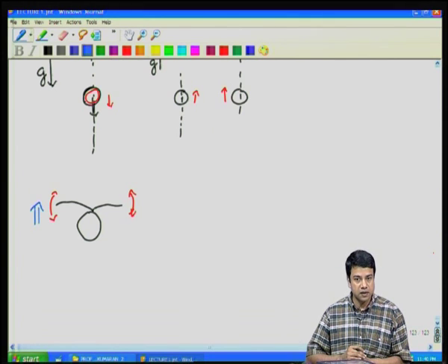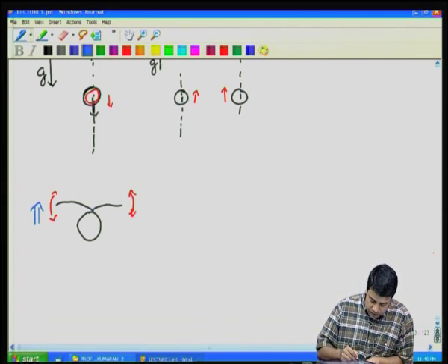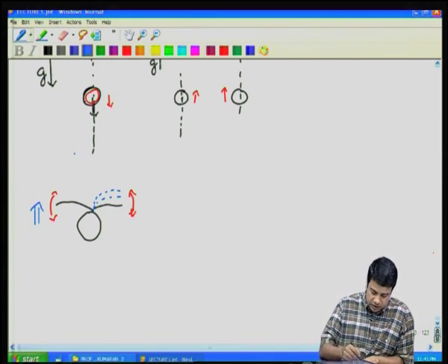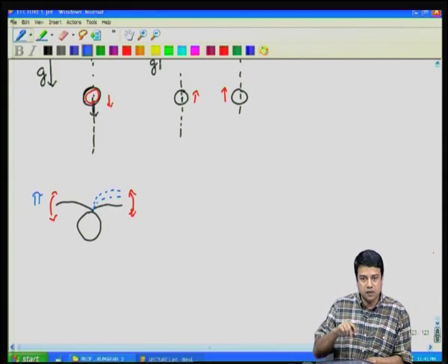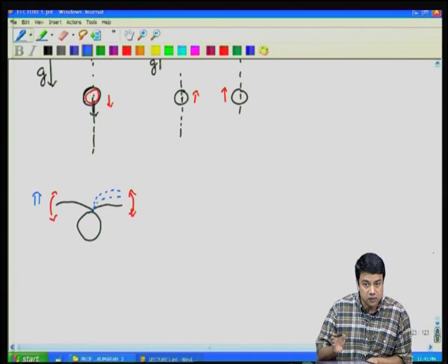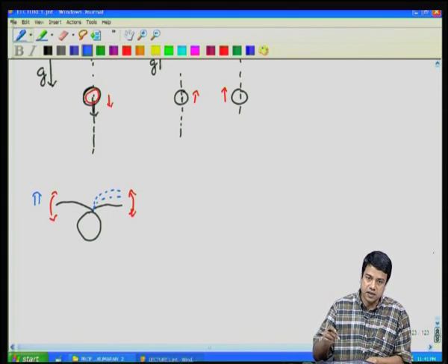However, for microscopic objects which typically swim at very low Reynolds numbers, this is not true, because let us say that the flagella undergoes a cyclical motion. If on the upstroke the object moves in one particular direction, on the downstroke the velocity at each point is reversed to that in the upstroke. So, that means that the velocity in the fluid at each point is reversed.